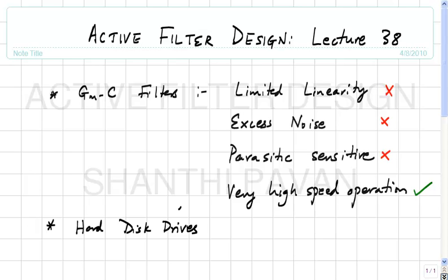That is the kind of SNR you require finally at the Viterbi end to decode bits with sufficiently low bit error rate, which means that if you need finally 25 dB or 30 dB, then the analog front end must have 1 bit more, so must be slightly better, so that the non-idealities in the front end don't impact the bit error rate finally.